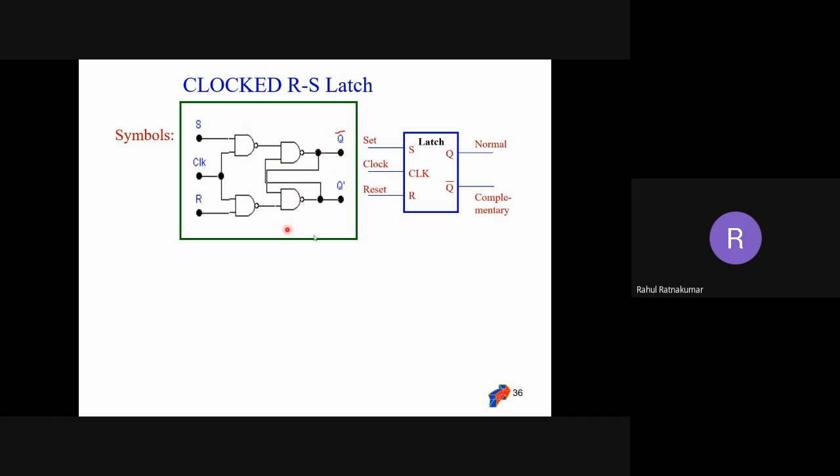Again, this is actually a NAND latch, and we are connecting a clock so that the latch can be a clocked latch, right? Flip flops, as you already know, are edge triggered, or you can say they activate on the positive or negative transitions. So they are flip flops. Even though you connect a clock to a latch, it becomes a clocked latch because it is still working on level, not on edge triggering, high to low, positive edge or negative edge, right?